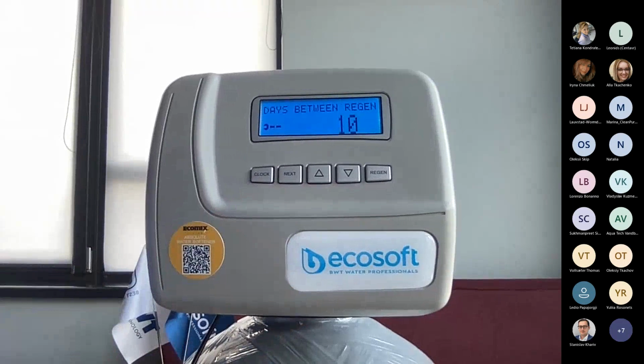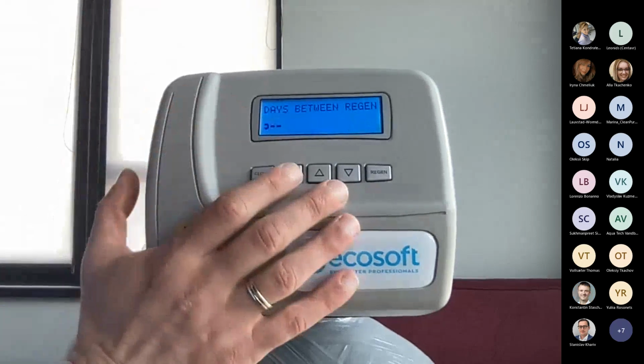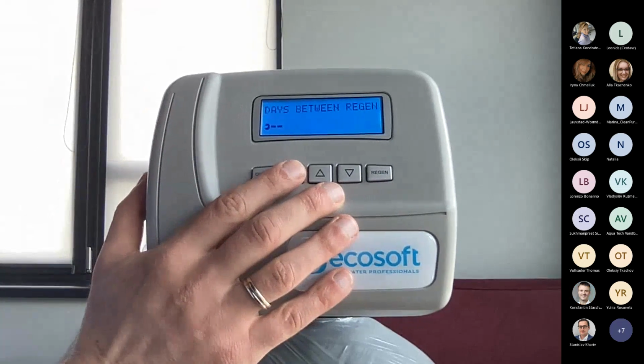When you have iron of more than 5 ppm in the water, I would always recommend to leave the filter on, and not switch off the valve, not switch off the water, and keep it always fresh. Because if the iron is very high and you don't make regeneration every 10 days, then you may foul any media you use for iron removal.